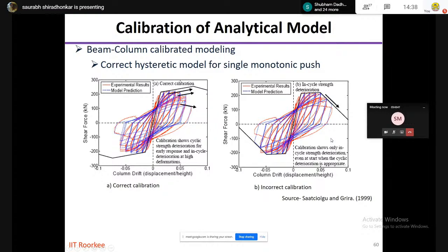So if you can see, the red one over here is the actual hysteretic loop which is obtained from the experimental study. In the experimental study, we actually cast a reinforced concrete column, and it is subjected to incremental load in the laboratory, just like a pushover analysis that we have seen. It is pushed into the inelastic range, then taken back and pushed in the other direction. This cycle is done over and over till it reaches the ultimate point.